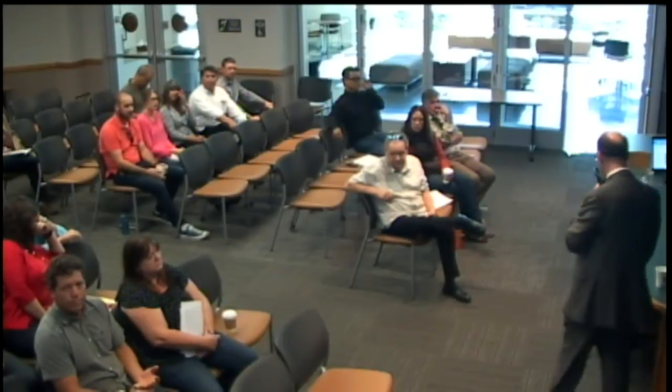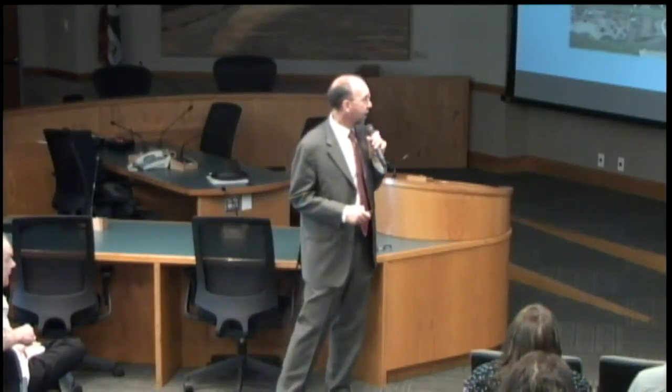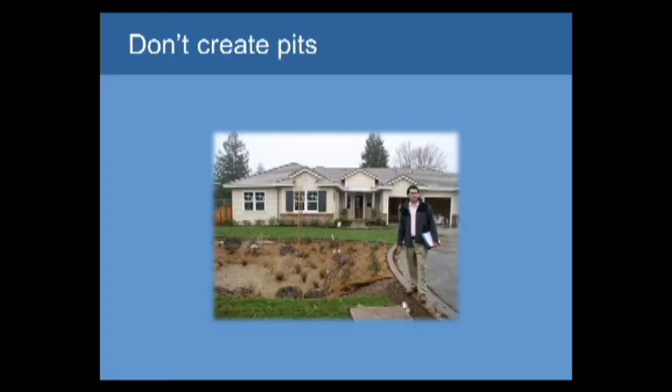So getting back into drainage design, this is my friend Dan Freeman. He's a developer in Contra Costa. And this is a house that he had just built. This was in 2005 or 6. And we were just learning about this bioretention business. And he had hired an engineering firm, and a young engineer had taken the elevation of the downspout on the back side of this house, which they had decided to drain to the bioretention facility, and had laid it out at a 1/4 inch per foot drop. And then when he figured out what that elevation was out in the front yard where the bioretention facility was to be, that's the elevation that the bioretention facility was built at. It actually got approved and built.